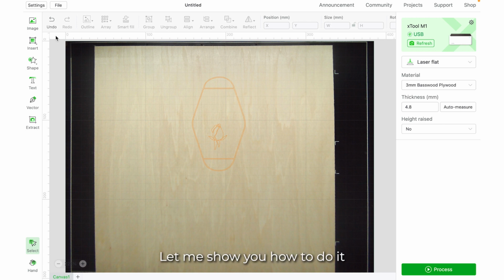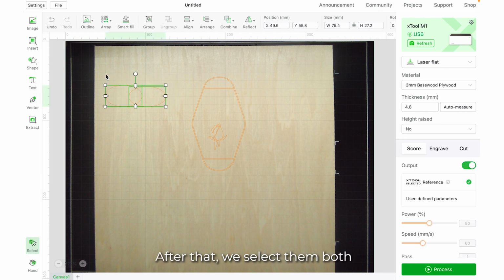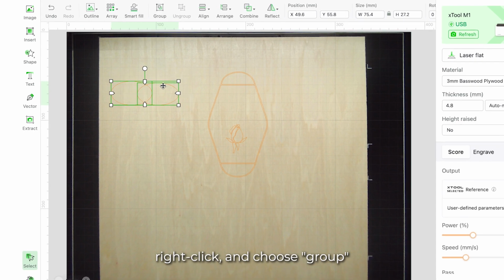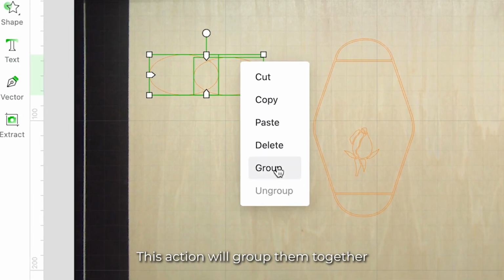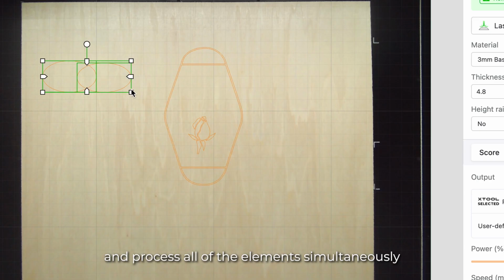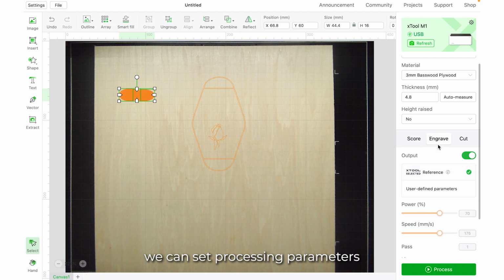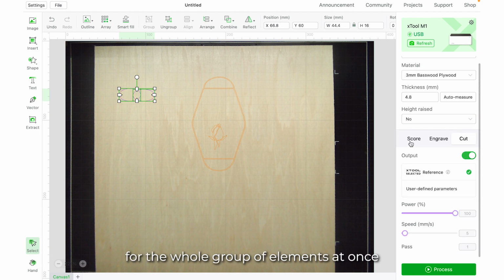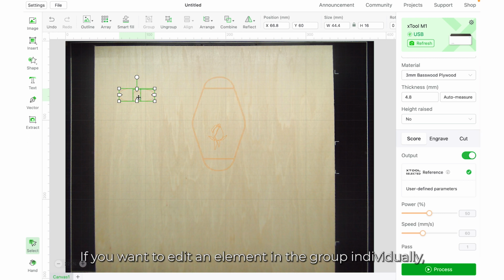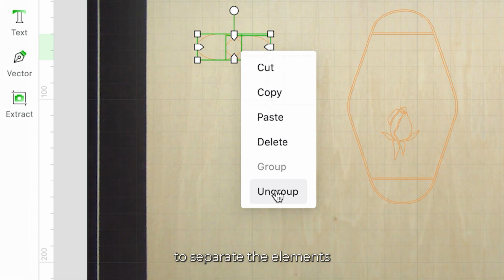Moving on, if you need to work with multiple elements at once, we recommend using the group feature. Let me show you how to do it. First, we need to draw two graphics. After that, we select them both, right-click, and choose Group. This action will group them together. Once done, you can move, scale, and process all of the elements simultaneously. What's more, we can set processing parameters for the whole group of elements at once. If you want to edit an element in the group individually, right-click again and select Ungroup to separate the elements.